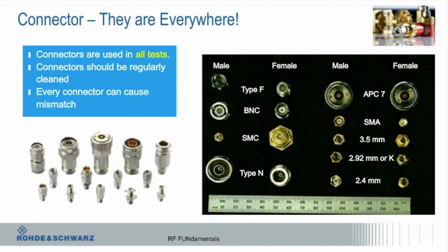Okay, go ahead. You should add the little micro connectors, U.FLs, and everything else to this too, because everybody's migrating from those. Yeah, it's a good point. The only thing is, I'm familiar with all of them, but I don't know the specs on a lot of them, and I don't think any of those are precision connectors. I think MMCX might be, but you don't typically see even a cal kit for those, right? I know what you're saying. It's a valid point. I don't get to make that decision, but it's a valid point.